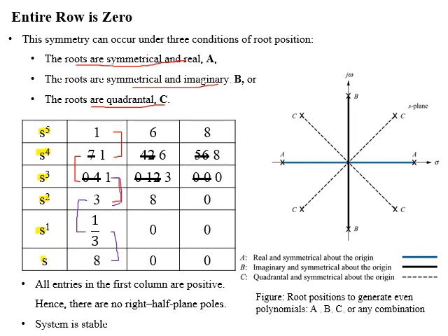If there exists a sign change after the auxiliary polynomial, then one pole will be in left half plane and second pole will be in the right half plane. As all entries are positive, we don't have any right half plane pole. So our closed loop system is a stable system.